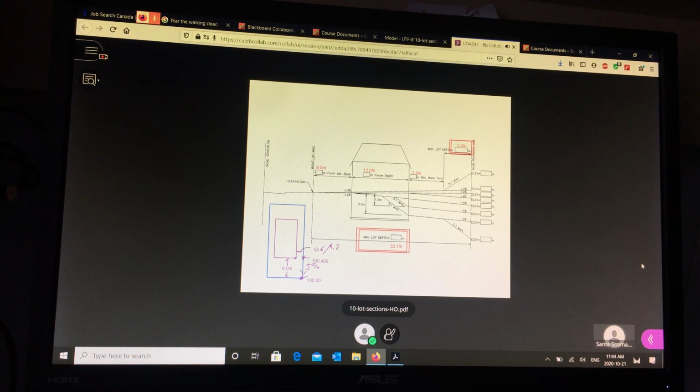Now, when you look at a cross section of a lot, I'm just going to draw one half. I'm going to look at this section. You see the wall of the house, and then you see the property line. Whatever the elevation is opposite the corner, the elevation at the house is going to be higher by about 0.15 meters.